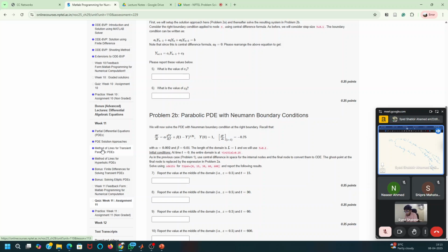But this is the only way if you have stiff systems, where implicit solvers like ODE15s or ODE23s are a good option. If your system is not that stiff, you can directly use ODE45, which is very stable.